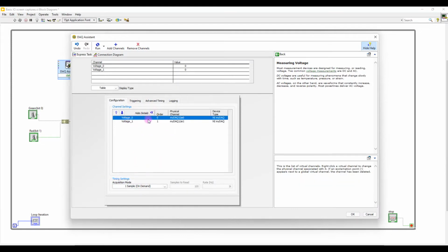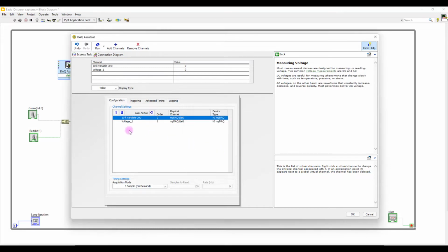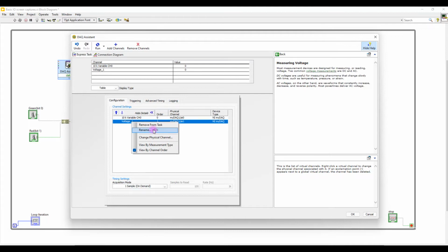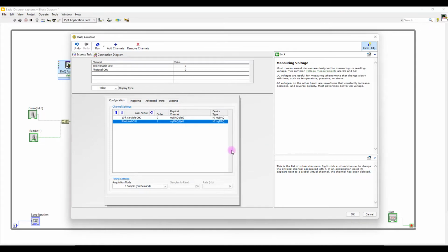And we'll go to details. The first channel, channel 0, is the 10K variable. So I'll change the name here. It's useful when you troubleshoot. So 10K variable. And maybe we can put channel 0. That doesn't hurt. And the other channel, I'm going to rename that. The other channel is going to be the photocell on channel 1. And as I said, it's also called a light dependent resistor.